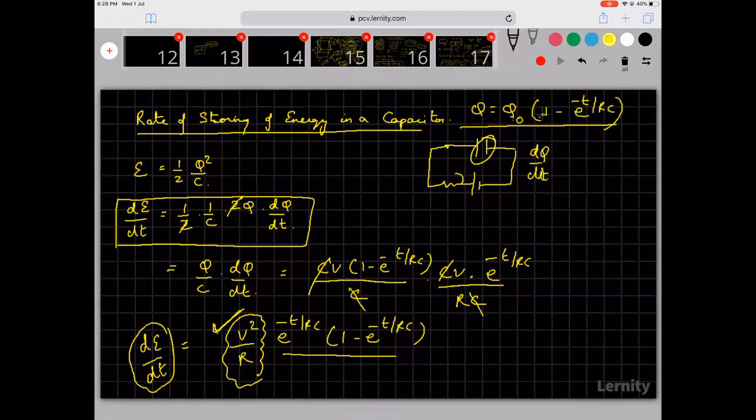So this is constant. So minus Q0 e power anything, the differential is e power this, divided into 1 by RC, minus 1 by RC. So the minus minus became plus. So that is how we got the value of dq by dt. We differentiated this quantity, and by differentiating it, we got dq by dt.